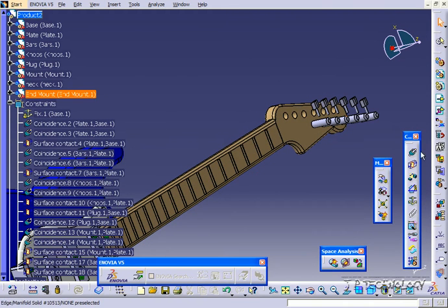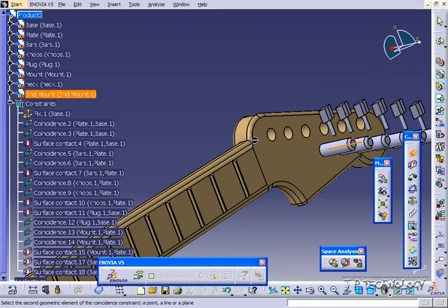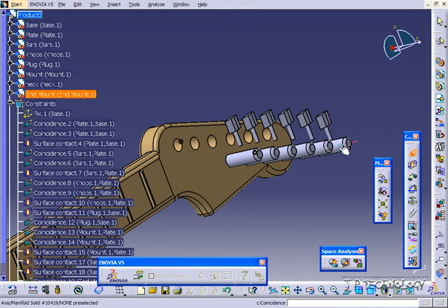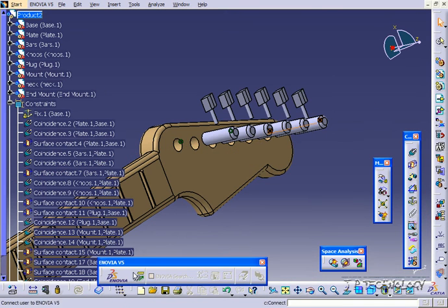And let's line these circles up. So click coincident, click that circle there, and do the same at the end. And this is just like the other part. You can do each of these as individuals. I threw it all into one part so that it's easy to assemble. Click update, and now they're lined up.